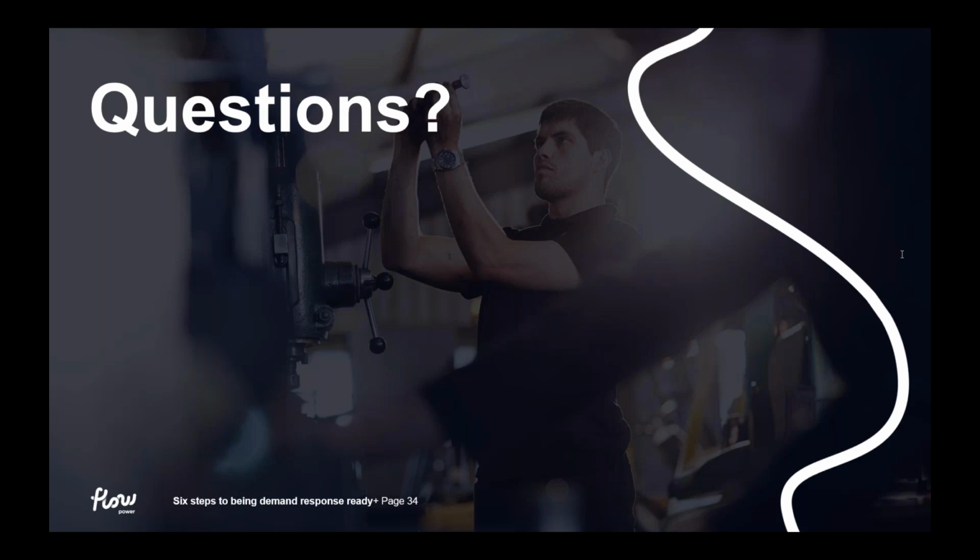So demand response is definitely easier for some customers than others. Cool stores, pumping loads, things where you can store energy. As Nat said, manufacturing is one which typically hasn't done as much in the past if there's a process running. But the market cap for wholesale is $14,700 a megawatt hour. At that point, if that's going to run for a couple of hours, almost every customer will save money. So some of our customers will just set it at that, and they will only do demand response at that level. Whereas someone that can do it easily would do it at $300, $200. Yep.